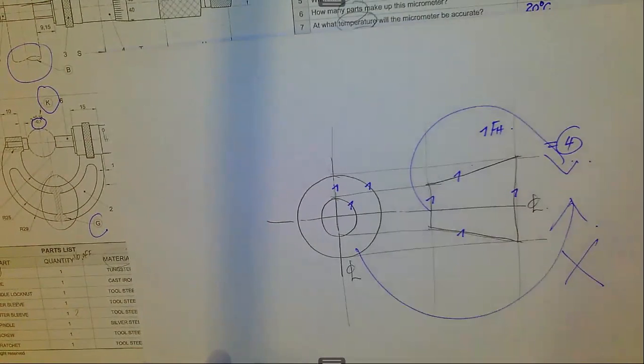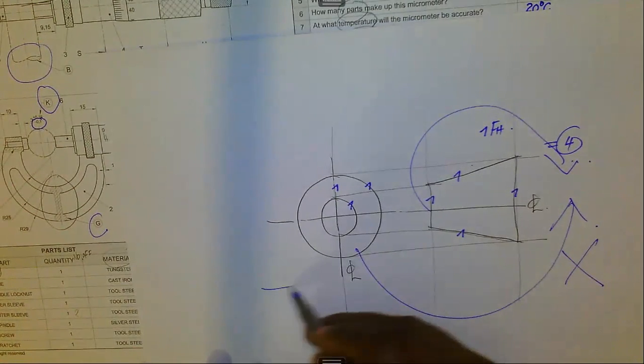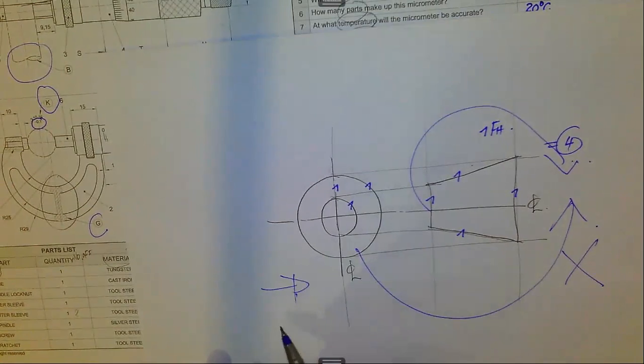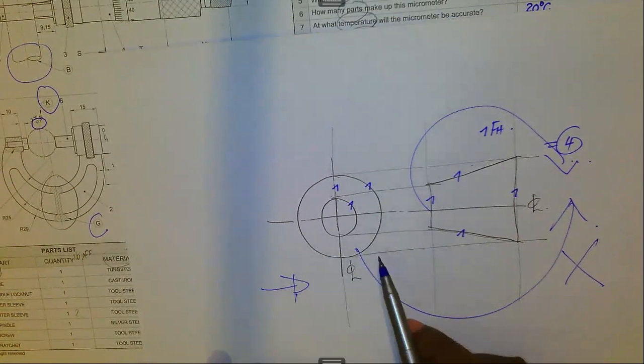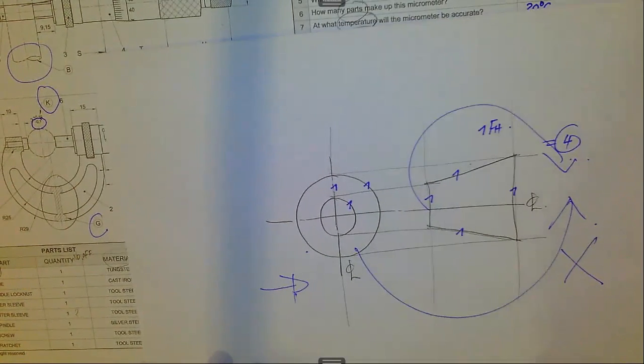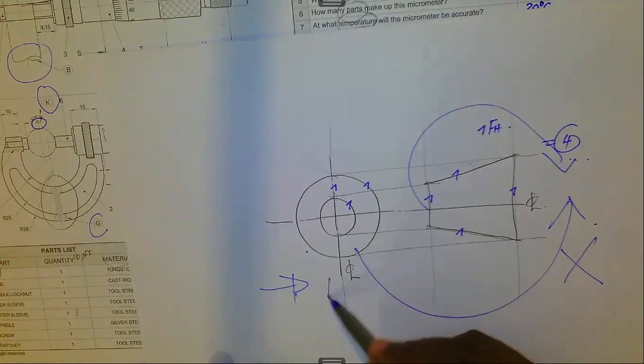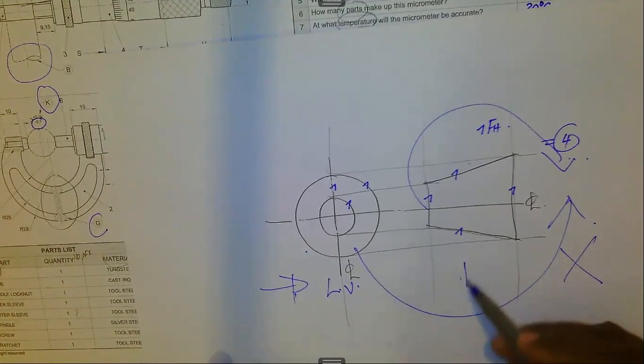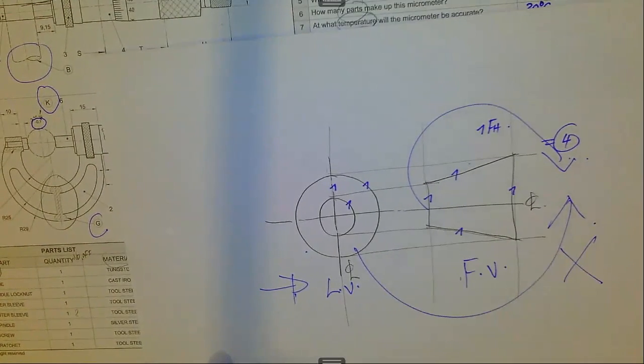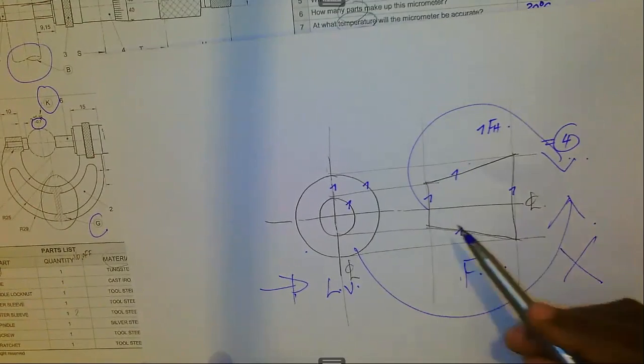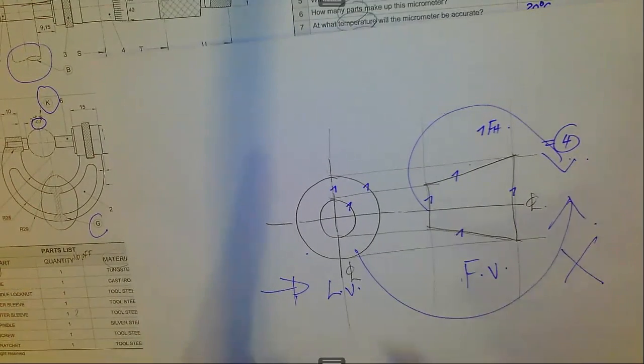Third angle orthographic projection: what you see from the left is drawn on the left, what you see from the right is drawn on the what? On the right. So this one basically is our left view and this one is our front view. But at the same time, we can also talk about this being the front and this being the right view.